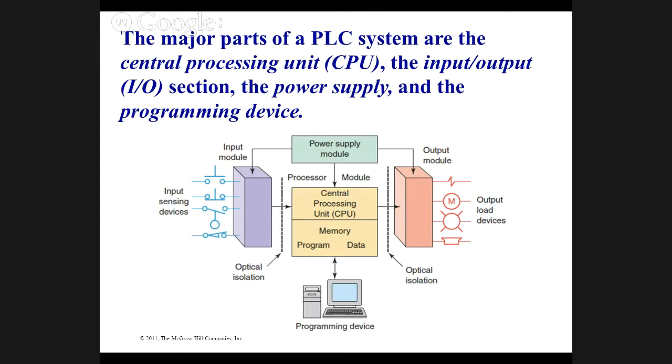But that's what it does. The power supply simply powers everything. It is easier to say it reads the inputs, it processes them, it runs the programs on the inputs, and then updates the outputs once the program is scanned. We're going to get into scan time in a little bit. Okay.